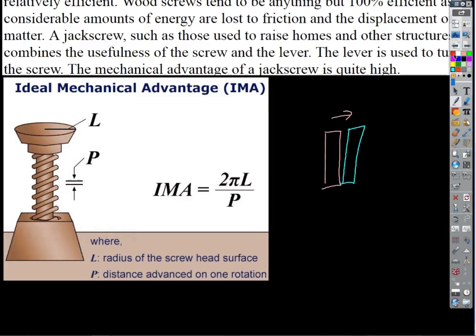One thing I could do is drill a large hole through this one, and drill a smaller pilot hole into this one. And I could put a screw through this hole so it just starts to bite on that one. And what happens if I turn that screw in then? When the head of the screw gets to here, what's it going to do? It's going to pull this one with it as this one bites into the wood, right? And you can develop tremendous forces that way. You can pull stuff together using a screw that you had no chance of doing with pliers or with a vice grip. I mean, you really get big forces, okay?